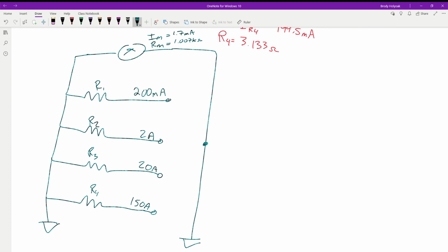Okay, here's a thought. What would you be using this type of meter for? A house. You could build a meter inside your house to be able to show you how much current you're using at any given time. And you could wire this into your circuits. Wouldn't suggest it, but you could. This way you could be constantly monitoring. 150 could be how much current you have total in your house. 20 amps could be a single breaker. This could be a single device, and this could also be a single device. Phone chargers run about 2 amps, 2 amps to 5 amps, depending on the type.